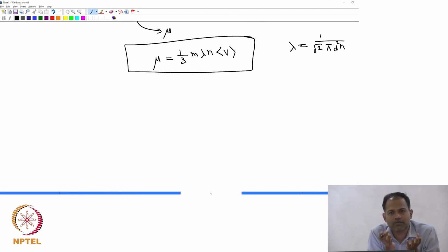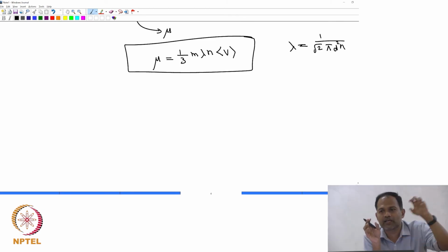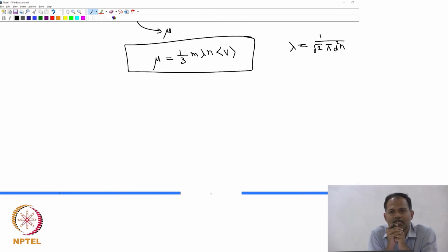The mechanism is similar. There also there is a momentum transport. The only difference is that the liquid molecules do not undergo such large fluctuations, they do not collide with each other and go away somewhere else. So, that picture is not really correct, and that is why we are not getting the right expression for viscosity, but the momentum transport is still there, and the connection between momentum transport and shear stress is still true for liquids.